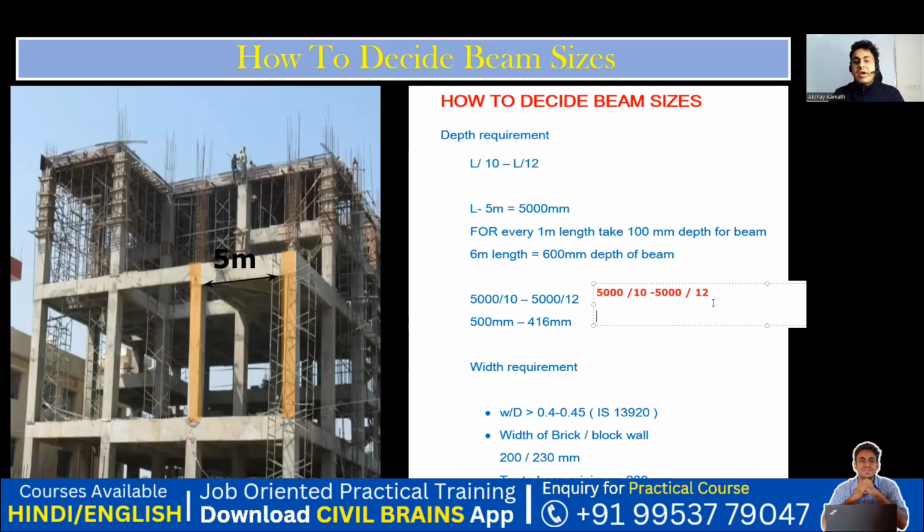So 5,000 divided by 10 comes out to be 500 mm. And 5,000 divided by 12 comes out to be 416 mm. It is L by 10 to L by 12. So now I have an idea that I can keep the depth of my beam between 416 and 500. So what is the best size I'm supposed to take? I can go with 450 because 450 is the standard size we go with. You can even take 425, but we'll go with 450.